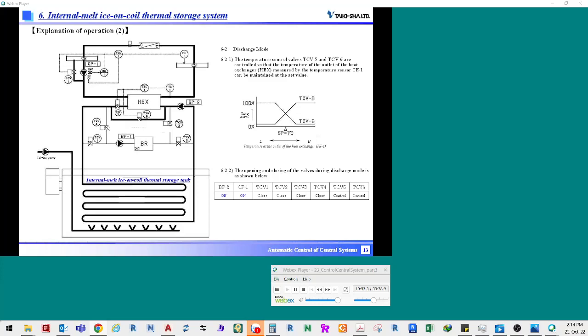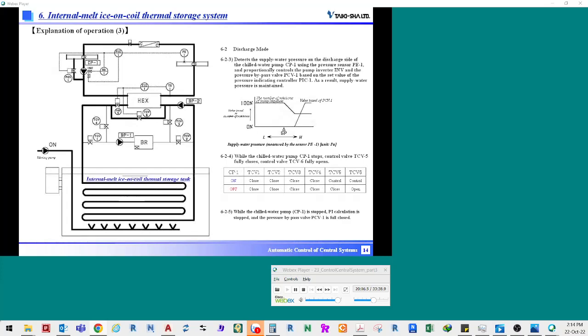It is used when the heat transfer load caused by outer walls is considered during air conditioning. Use the equivalent temperature difference. Effects of the sunlight and related to the heat accumulation are also considered. Otherwise, use the temperature difference between that of the outdoors or the next room and that of the target room. If the next room is not air conditioned, in general, the temperature between the outdoor temperature and the indoor temperature should be considered.